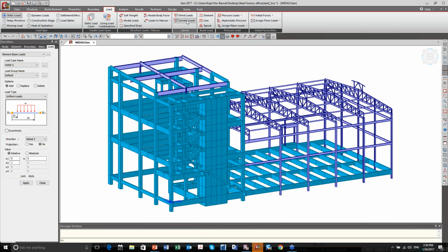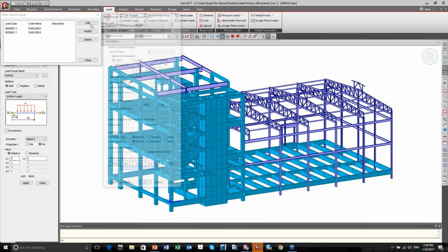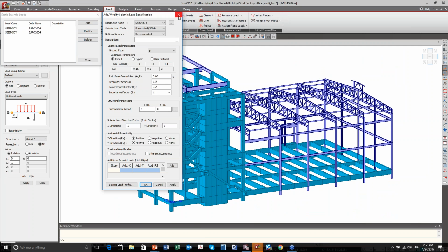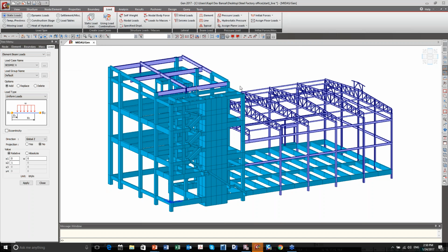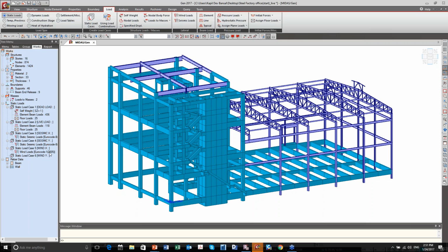And we also have the seismic load auto-generate functions, but this one maybe I'll skip because for steel structures we usually do not consider the seismic, but you can automatically generate this static seismic load and also response spectrum seismic load in Singapore National Annex. Okay, so now I will show you some other lateral load, the imperfection load.